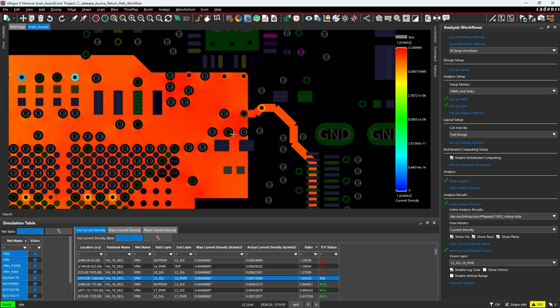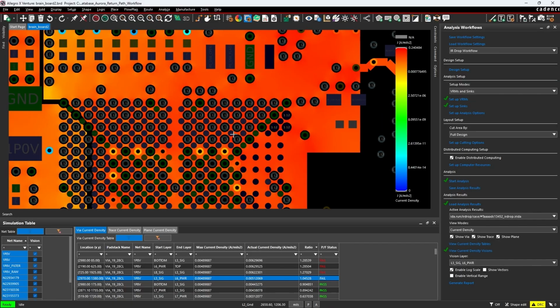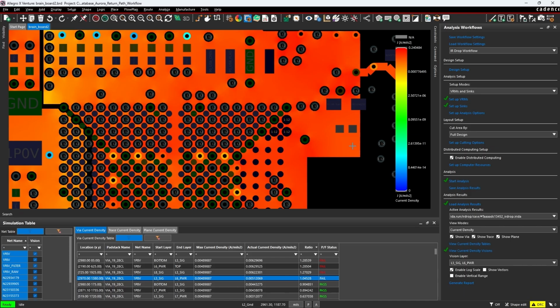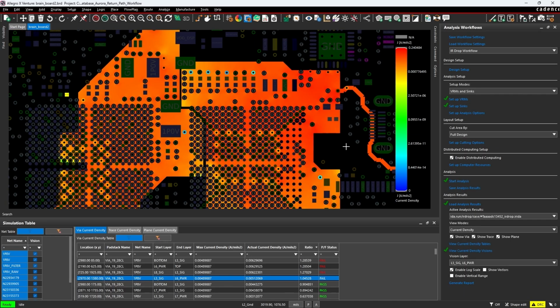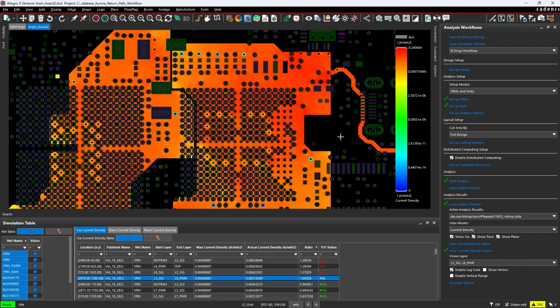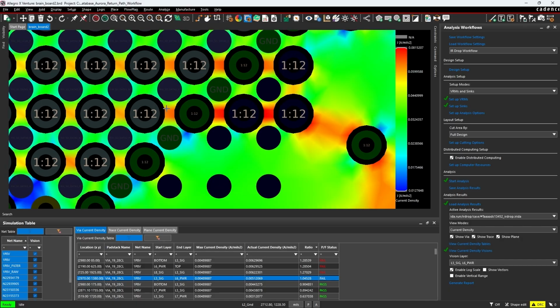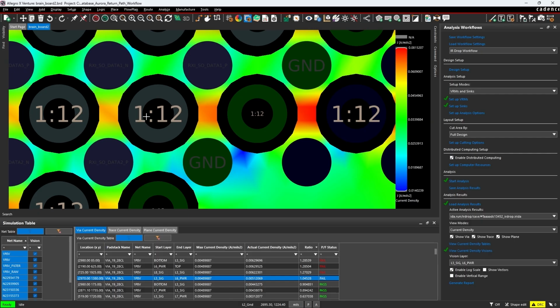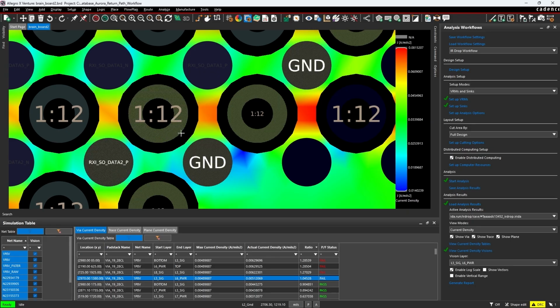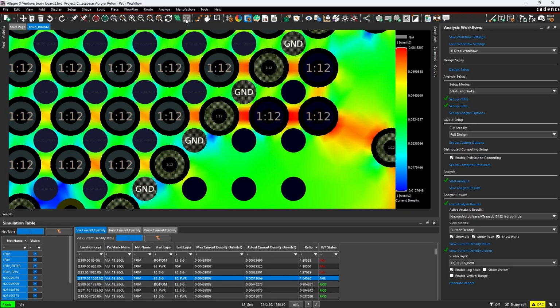The ways to solve this problem, how do we fix this? Well, you can again add more vias in your higher current density regions. So that's a solution. And by vias, I'm specifically talking about oftentimes not just your core current via, but you want a via for your signal or power and a ground return nearby. See what we've got going on here? Because of that, we have the electromagnetic field having its signal and then also a return region or adjacent return set of vias to push that signal through the PCB dielectric.